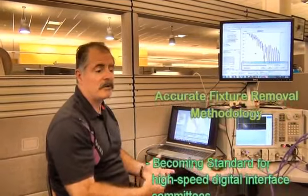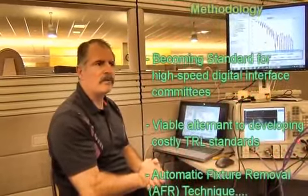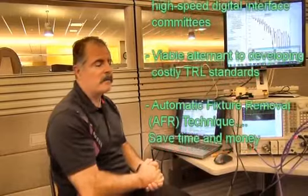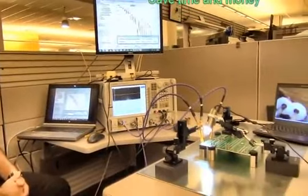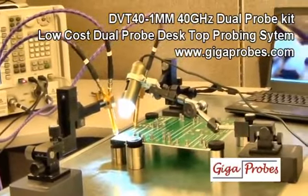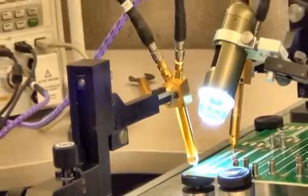It's becoming a standard in many of the high-speed digital interface committees. And so rather than struggling with through reflect line calibration kits, which require a lot of time and money, you can actually save a lot of time, a lot of money, and use this newer automatic fixture removal technique. And the probing system for this does not have to be extravagant or sensitive or fragile. You can have a very robust probing system that allows you to make a wide variety of measurements in high-speed digital applications. Thank you for your time.